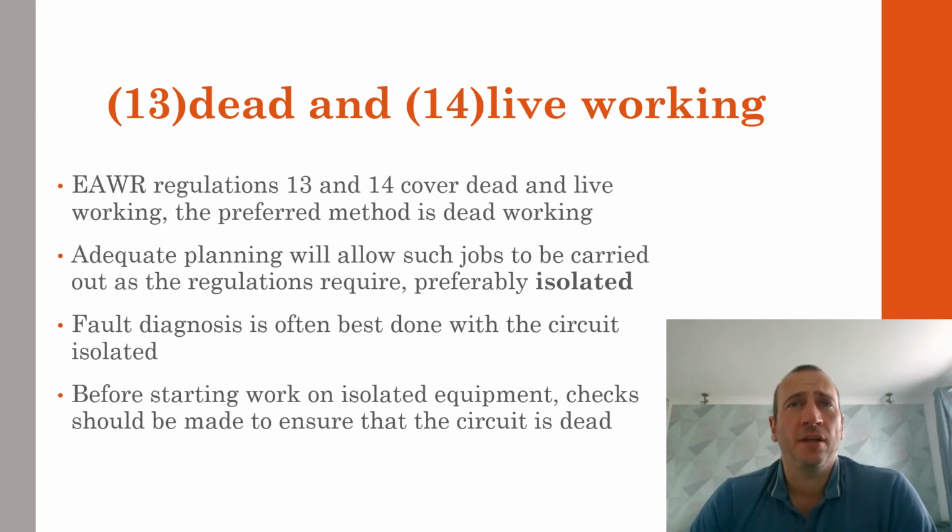The Electricity at Work regulations number 13 and 14 cover dead and live working. The preferred method is always going to be dead working. In Regulation 13, which covers dead working, it states that precautions shall be taken to prevent items made dead from becoming live. This essentially means that we should always safely isolate a circuit before beginning work.